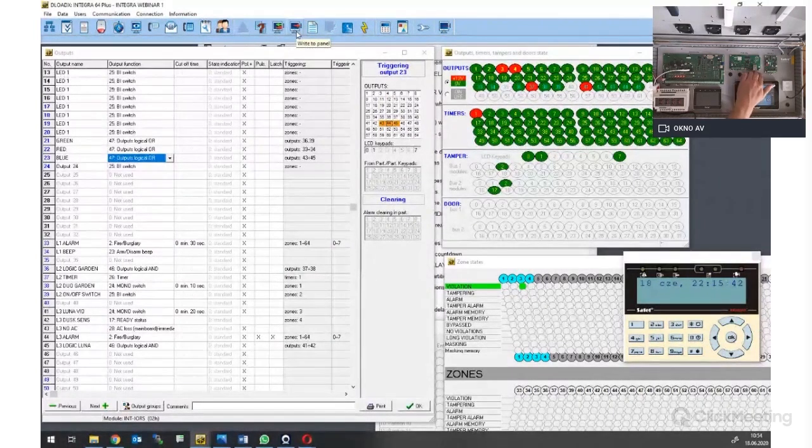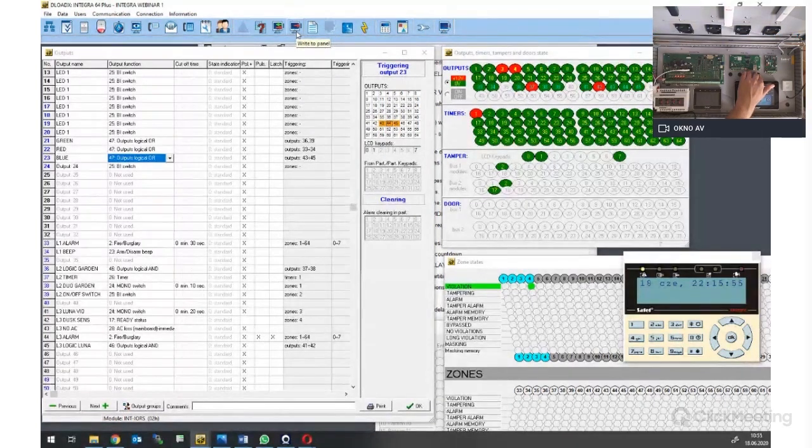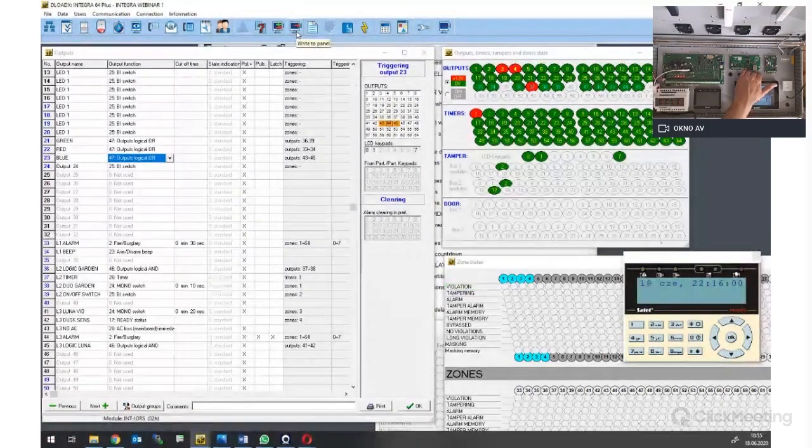Okay. If just the dusk sensor works and the Luna works, then my logic works and I have lights. Of course, when the 20 seconds from the Luna turned off pass, everything goes dark, turned off. If there is an AC loss, so I will turn off the AC, you see the light.